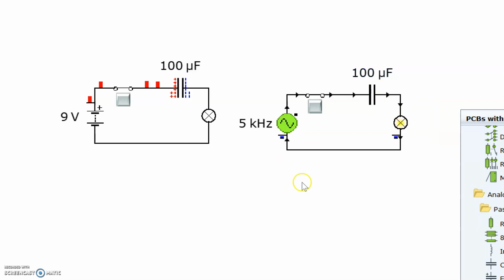So just to show you there that capacitors do block DC. DC cannot flow through a capacitor, whereas AC can. So capacitors are also used as filters for blocking out any spikes or any unwanted noise in audio circuits and so on. Okay, so hope you found this interesting. Just a quick look at charge rates of capacitors and how they work.